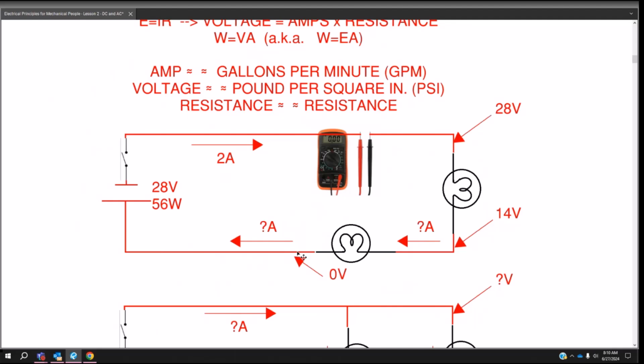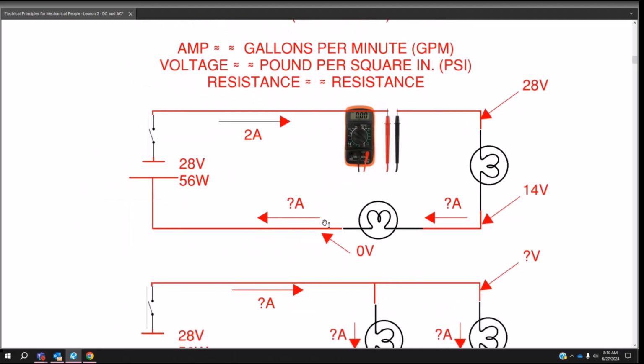I don't think so. The fact that the resistance is 7 at both of them doesn't mean you're halving the voltage again after the second drop. Think about it as the first one being the first half drop, and then you're dropping it all the way. So if you put the meter from before both drops to after both drops, you'll get 28 volts, because you're seeing 0 after both, right?